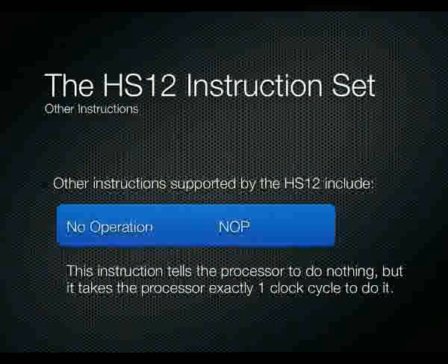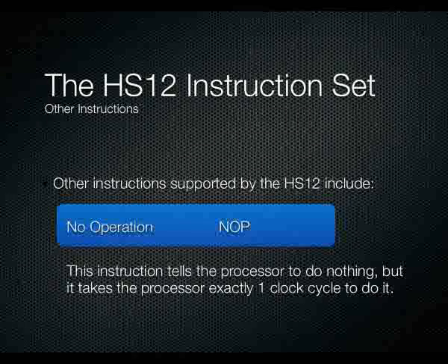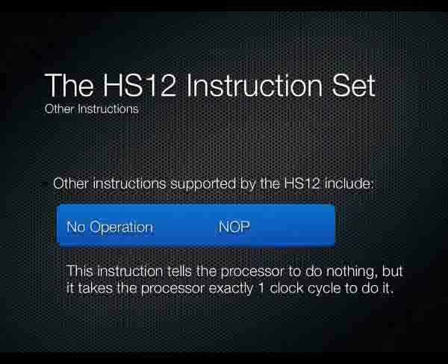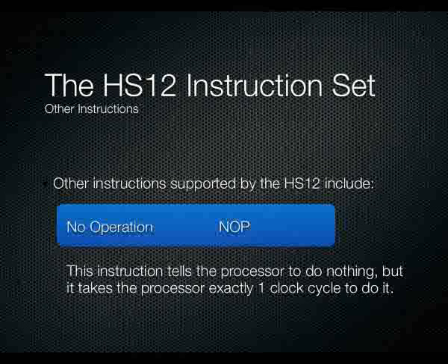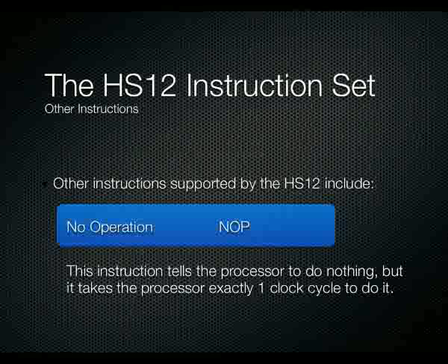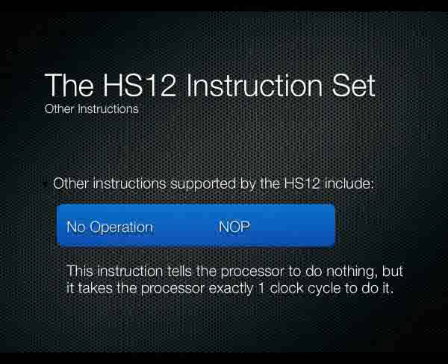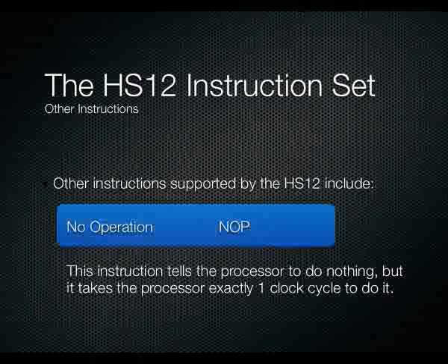There's one other really important instruction that we use, and it's the NOP instruction. Okay, the NOP instruction is a good command for doing nothing. It does absolutely nothing, doesn't change anything, doesn't change the status of the condition code register. It is what we call the no operation instruction. But one thing that it does do is it takes exactly one clock cycle to do nothing.